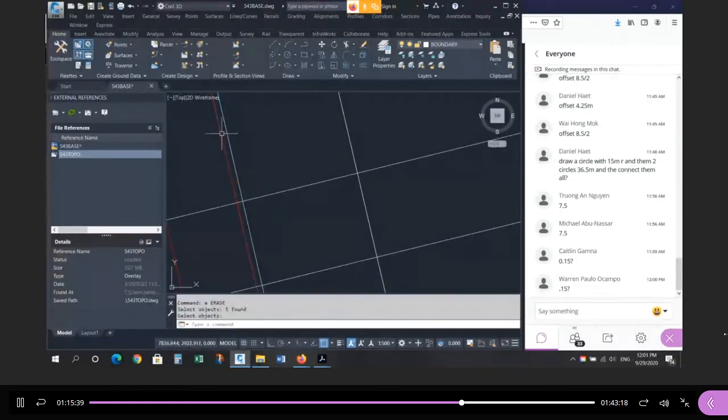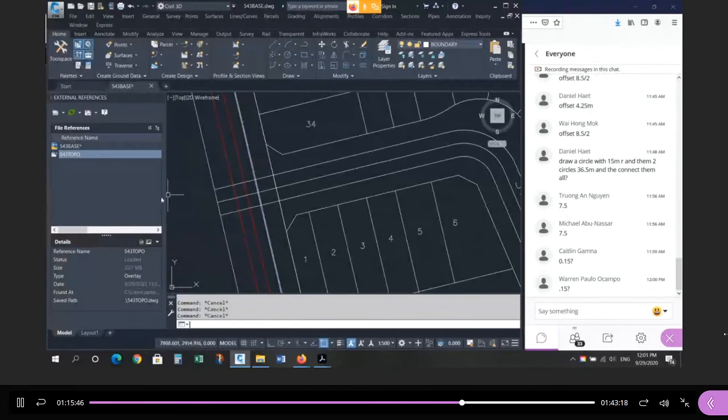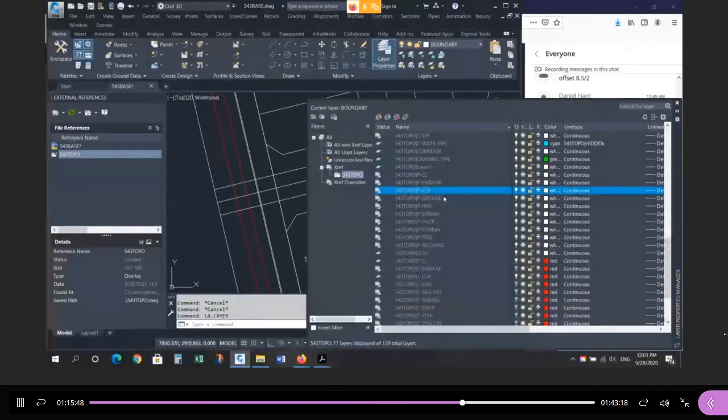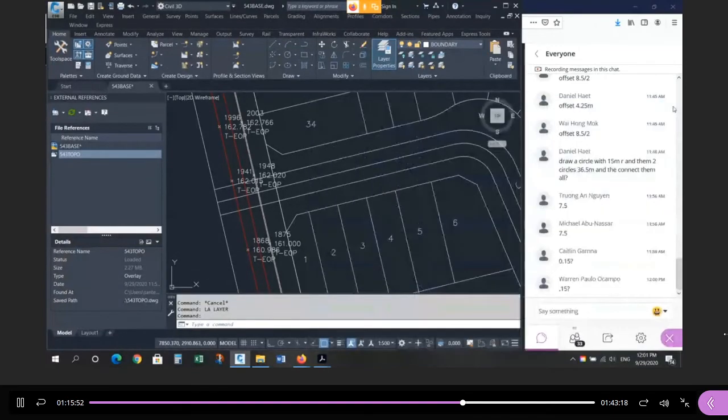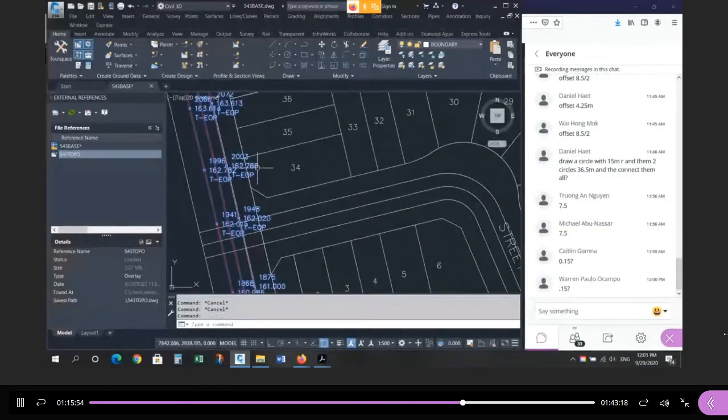So I'm going to delete this now. So I traced that edge. And remember, there's a bunch of dots there. See all the blue dots? Why? Because that is not a straight line. It wasn't drafted. It was actually from the survey. Remember? Connect the dots from edge of pavement to edge of pavement to edge of pavement on both sides of the road. So it's not a straight line. This is a design, right? It's offset from this line. Here, it's not drawn from the right-of-way. It's actually topographic information, connect the dots type work. Okay, so you got to be careful about that.